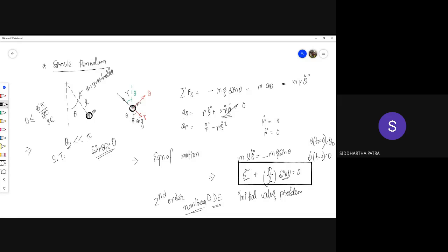Okay. Now imagine, instead of this equation being in time, the derivatives were with respect to x, a spatial coordinate. That would be a boundary value problem. For example, the equation of a beam, EI W double prime equals minus M, is a boundary value problem, and you need to have the boundary conditions of W. Let's say it's a simply supported beam. So W at 0 equals 0 and W at L equals 0.